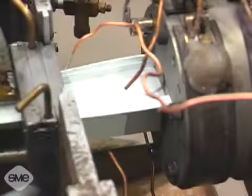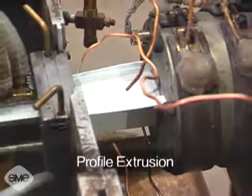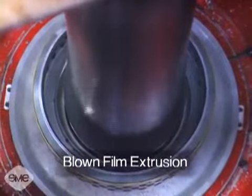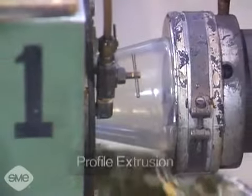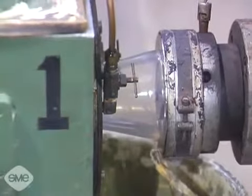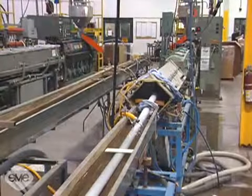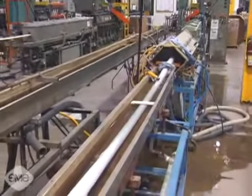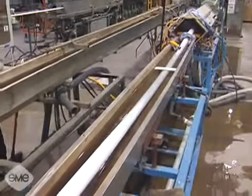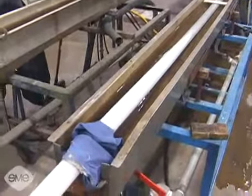Two of the principal plastic extrusion processes are profile extrusion and blown film extrusion. Profile extrusion is a horizontal process used to make long, continuous shapes having a constant cross-section or profile. The profile is extruded into a long horizontal cooling tank or trough filled with water. This water cools and solidifies the extruded plastic as it exits the die.